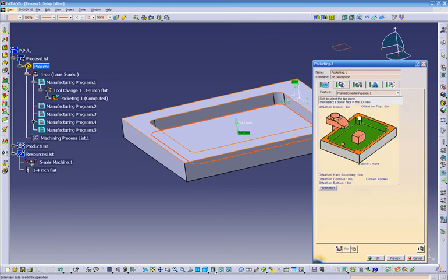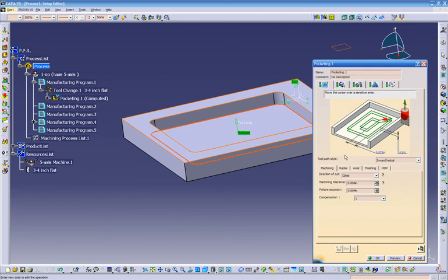And right now, because we selected the top, we can go back over here, and on axial, remember we just selected number of levels without the top. We can put the maximum depth of cut, and it knows that our top is over here.